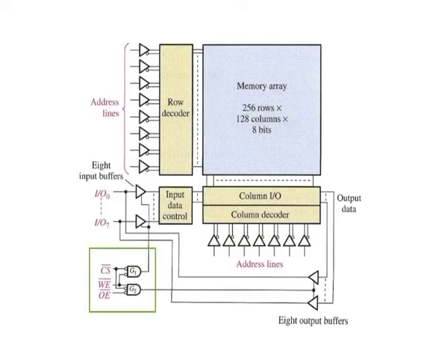In the read mode, the write enable input is high and the output enable is low. The input tri-state buffers are disabled by gate G1 and the column output tri-state buffers are enabled by gate G2. Therefore, the 8 data bits from the selected address are routed through the column input output to the data lines, which are acting as data output lines.